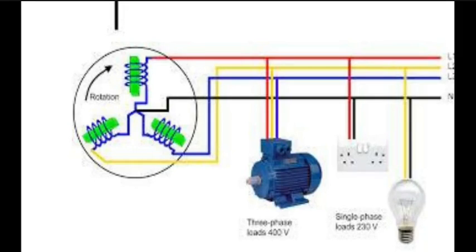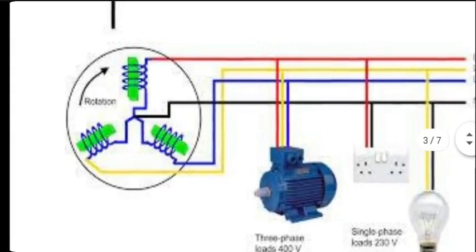You see, because one point is common. One of the terminals from each generator is connected together. This is why it is known as a Y connection. People also call it star connection. And 120-degree phase shift is there. The top one generator will have 0-degree phase shift, let's say. The one on the rightmost bottom will have, say, minus 120-degree phase shift. And the third one will have minus 240-degree phase shift. They can also have 0-degree, plus 120-degree, and plus 240-degree. That is also okay. Nothing wrong with it.